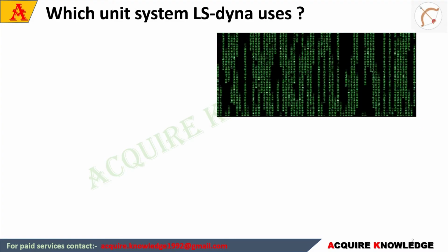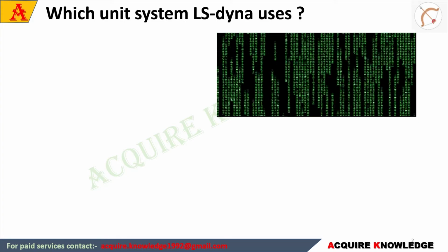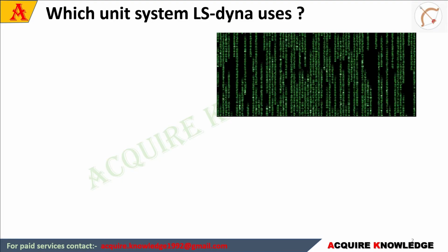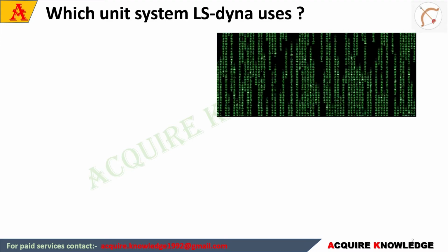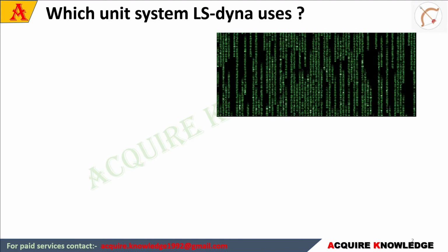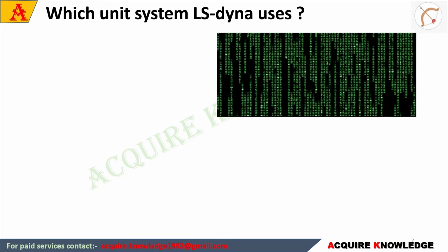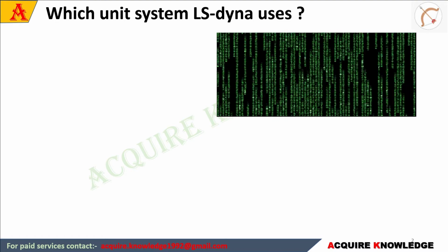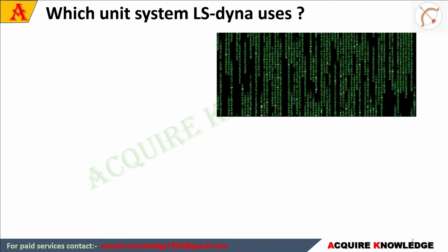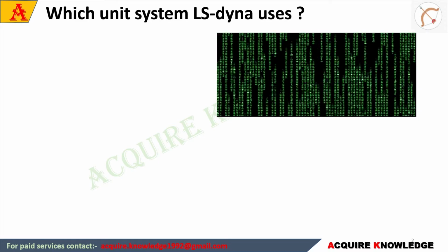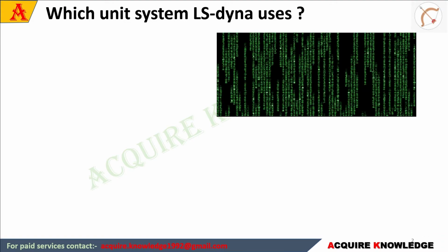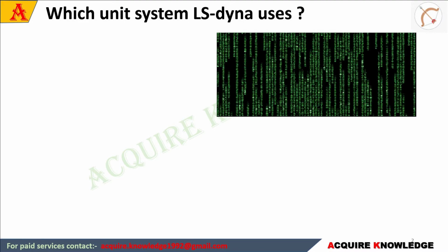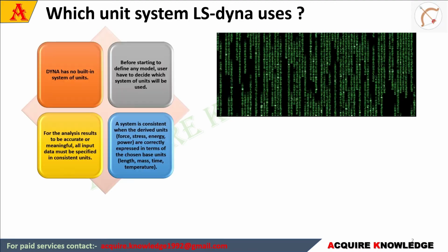Whenever we open a tool like LS-DYNA, ANSYS APDL, or Abaqus, we will see that it doesn't provide an option to enter the unit system. The reason lies in the fundamentals: FEA solvers only understand the values and not the units. To be more specific, the computer actually works on the values that are provided from any FEA tool. Now let's come back to LS-DYNA. To summarize, LS-DYNA doesn't have any inbuilt unit system. It's the core responsibility of the user to provide the input and interpret the results in a consistent unit system.